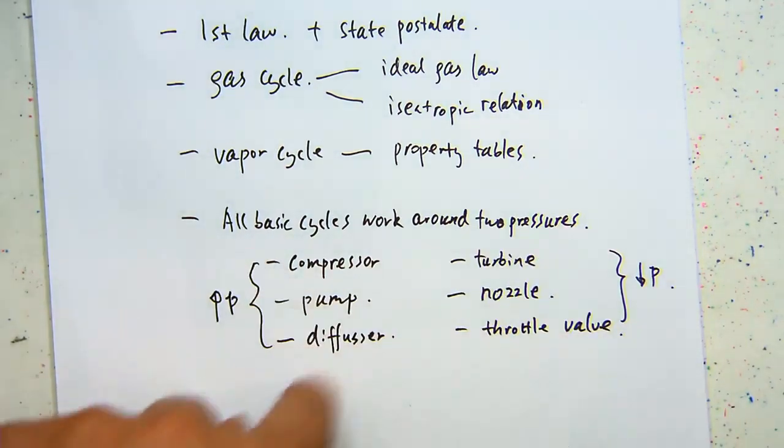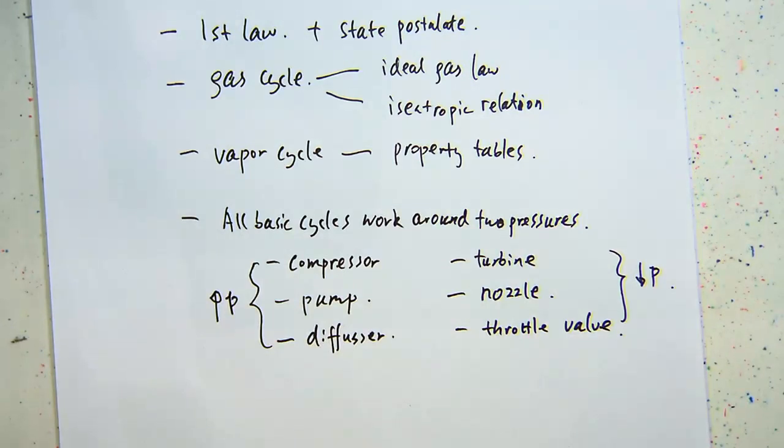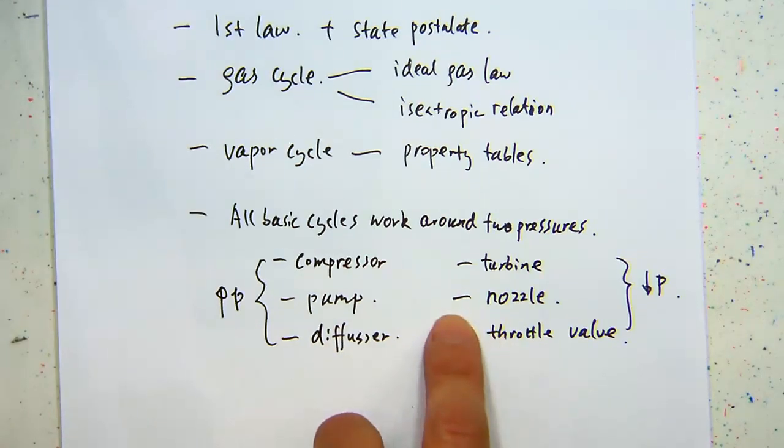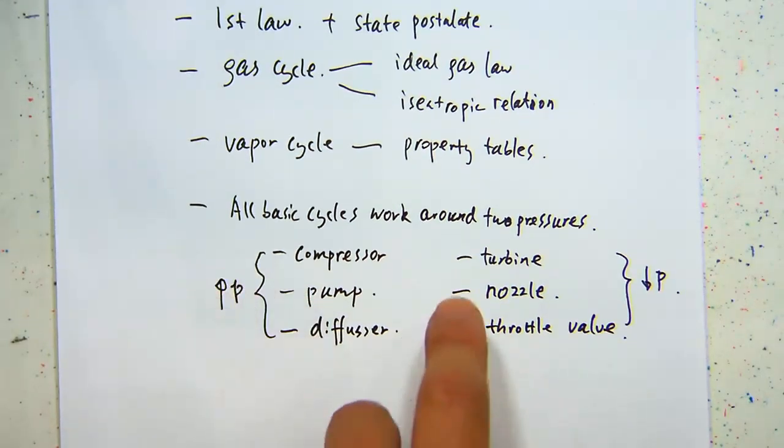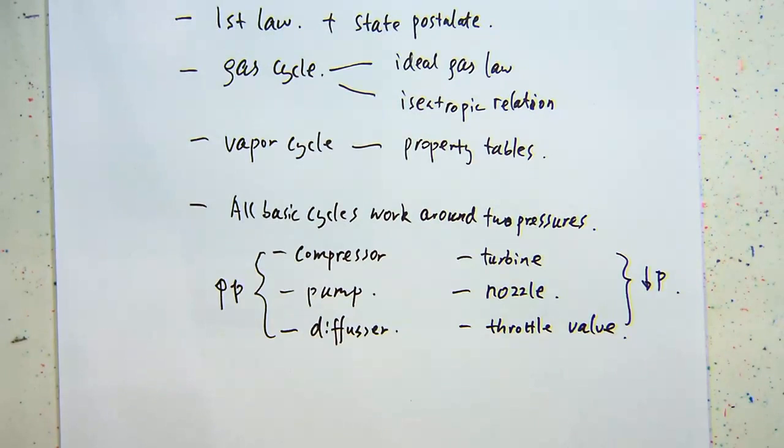But for the other processes, we can apply the isentropic process. Not necessarily the isentropic law, because if you're dealing with a steam turbine, you are not necessarily applying the isentropic law because you are not dealing with an ideal gas. But the process can be considered isentropic on the T-S diagram, which you have as a vertical line going down.